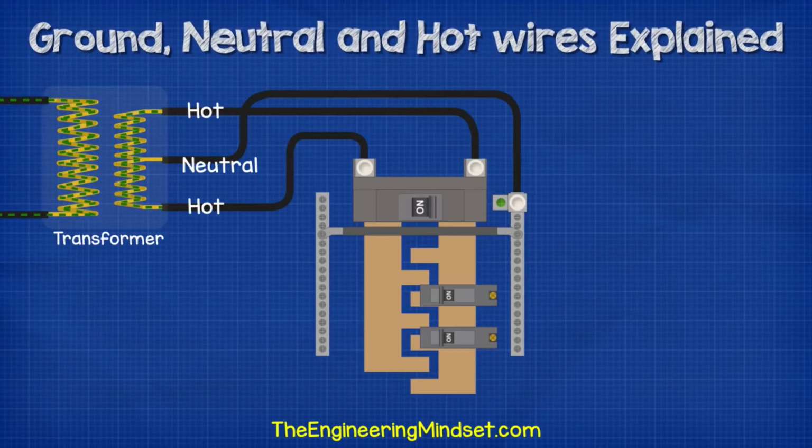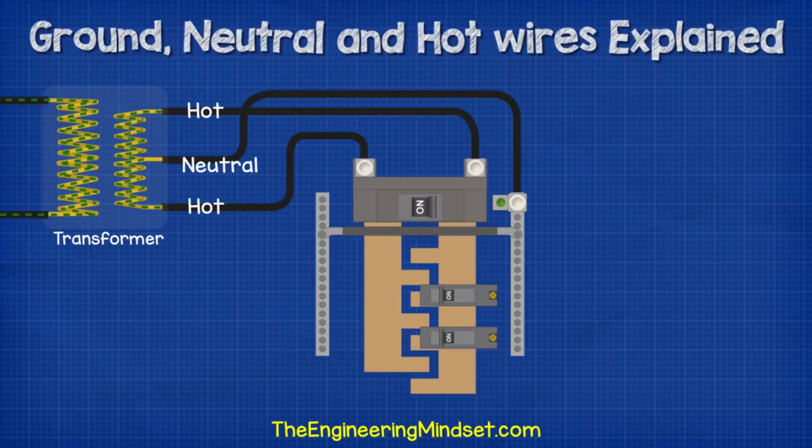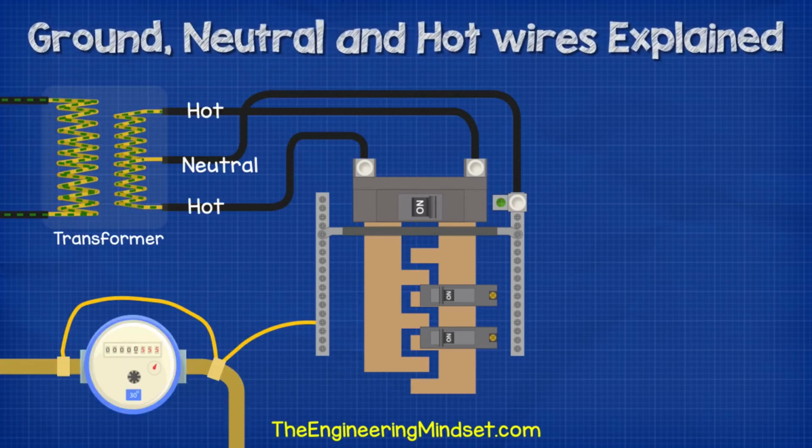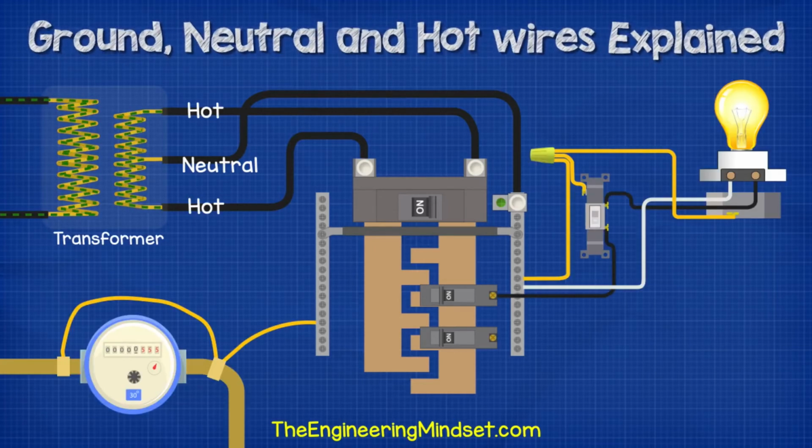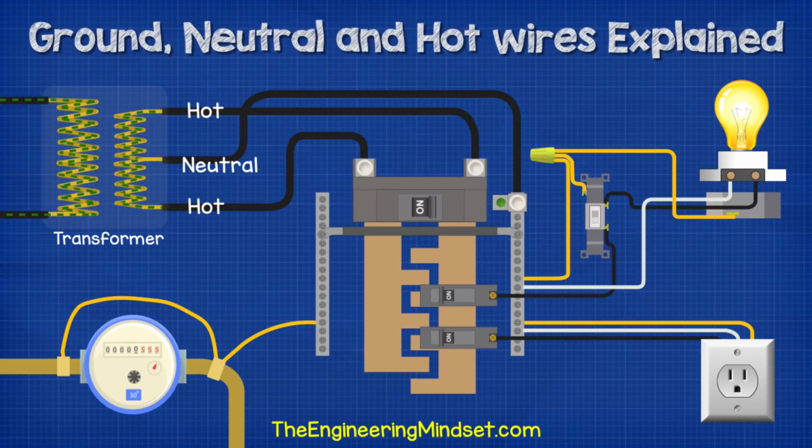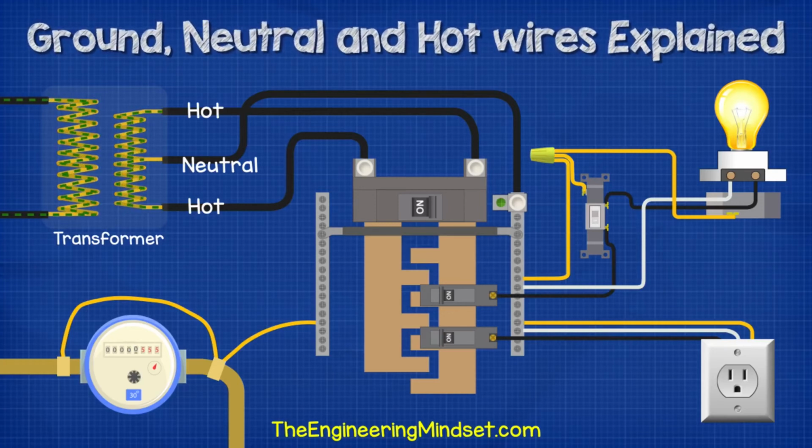We therefore connect the ground wires to anything that could potentially become a path for electricity to leave its circuit, such as the metal pipes, the metal plates on the light switches and the outlets or their boxes. We also need to run one to the outlets because often our appliances are made of metal or they're covered with a metal casing, things like washing machines and microwaves.